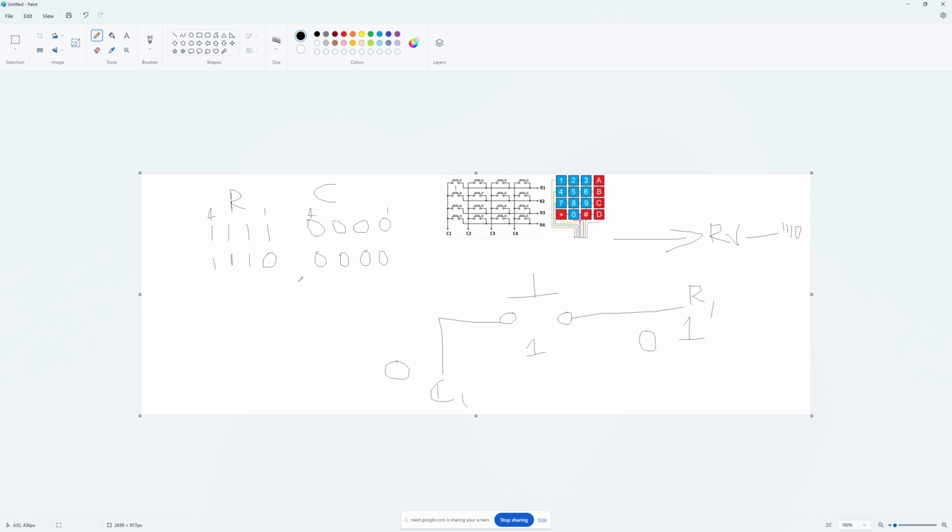Immediately the microcontroller will switch the voltage level by its own, making all the rows 0 and all the columns 1. We can do it, right, by managing the port pins. Okay. Now all the columns are 1, all the rows are 0. This is the value RV. And we have a new row value and new column value from the microcontroller.